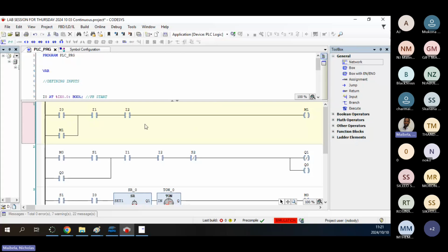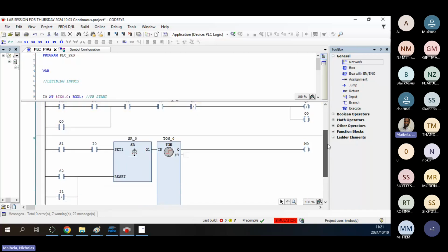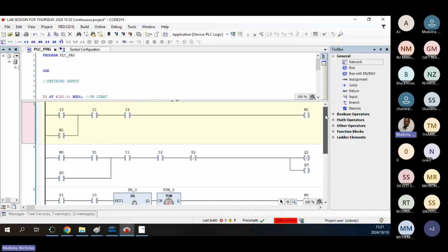So yes, the circuit that we have here, guys, is a stop start button, right? And it's latched. This circuit will assist us with keeping our circuit running infinitely. Now, remember when we were doing delaying advancement and delaying retraction, we swapped the M output.